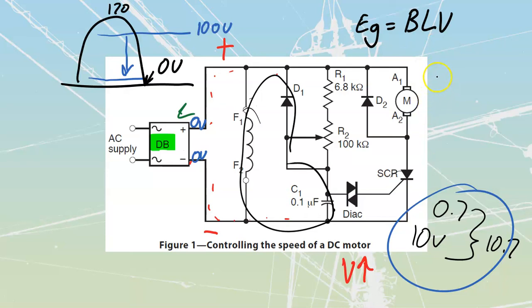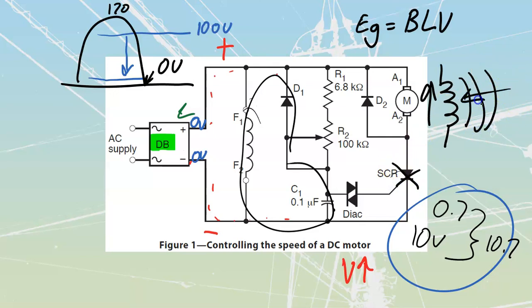It is also made up of coils of wire, and coils of wire have this thing called inductance. And inductance is an effect where we try to oppose any change in current. So if my current was traveling through before in this direction, see how it's negative to positive? If my current was traveling through before, all of those magnetic lines of flux that we have around there, when we shut this off, are going to collapse back inward and try to maintain that direction of current.